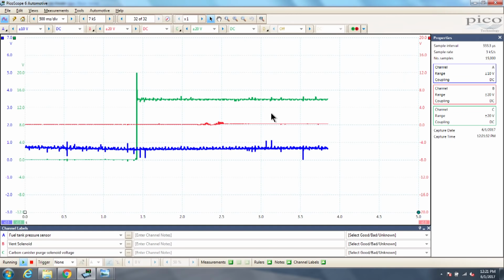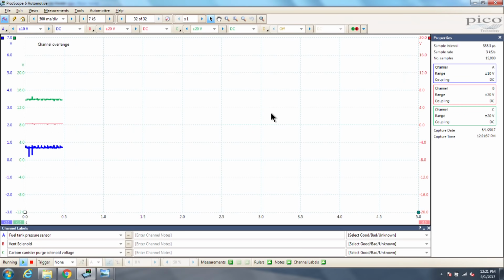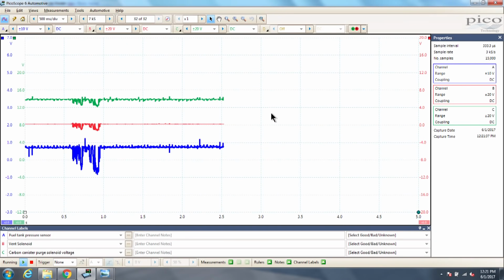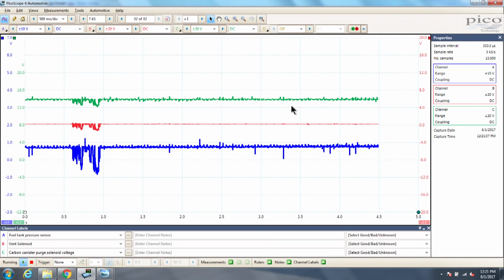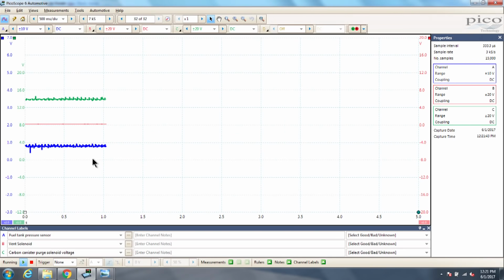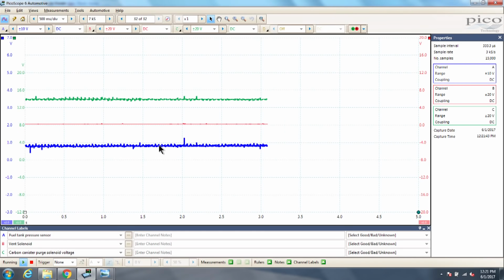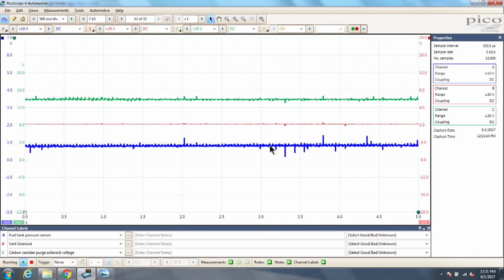So I ungrounded the purge. The purge is now closed. Our front door is closed. Our back door is closed. And now what I'm watching is this. I'm watching our fuel tank pressure over time to stay below our threshold.